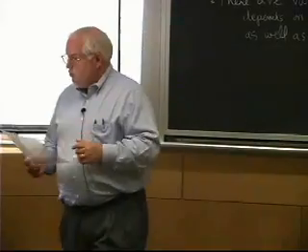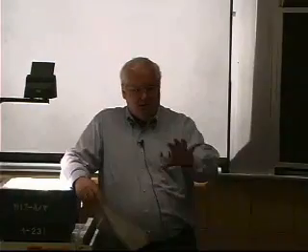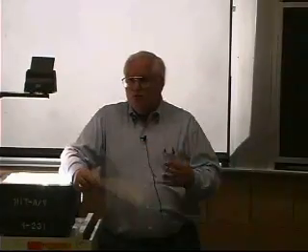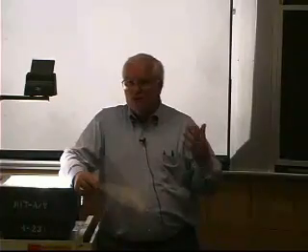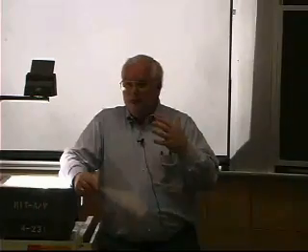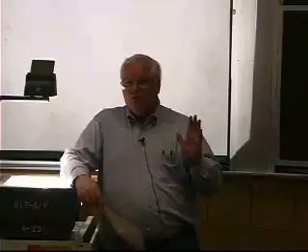However, just in general, when you go to do a failure analysis, one of the first things you should do is consider whether you can learn anything by doing some non-destructive tests to begin with. Typically, X-rays are great. You've got a failed component, something failed inside, and everybody's sitting there wondering, why did it fail? Well, what does a doctor do? If you come in complaining about something, why did your body fail? Well, he does an X-ray or some sort of test. Hopefully, if he's working on you, it's non-destructive. But you do a non-destructive test on the part. And a lot of times people just forget to do it.